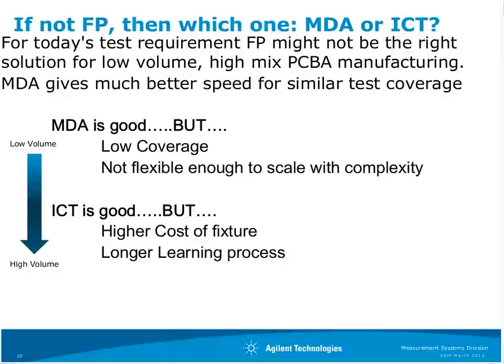We've highlighted some of the reasons that you might want to reconsider using flying probe test, since MDA can achieve similar coverage as a flying probe, but at a much lower capital outlay with much more efficient use of capacity and operating time. However, very often only matching the test coverage of a flying probe can't be enough reason to move from flying probe to an MDA strategy.